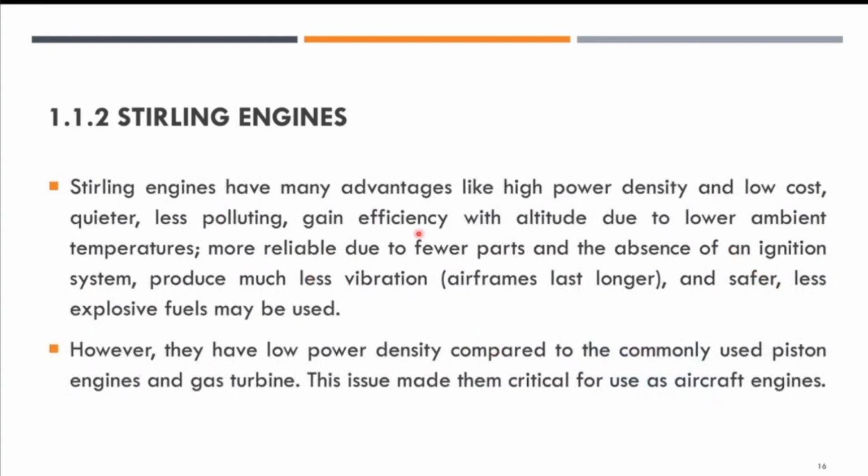Stirling engines also have many advantages, like high power density as well as low cost. It is also quieter, less polluting, gains efficiency with altitude due to lower ambient temperature, and is more reliable due to fewer parts because it's not that complicated. The absence of an ignition system also produces much less vibration. The airframe will last longer with this kind of Stirling engine, and it is safer, since less explosive fuel may be used.